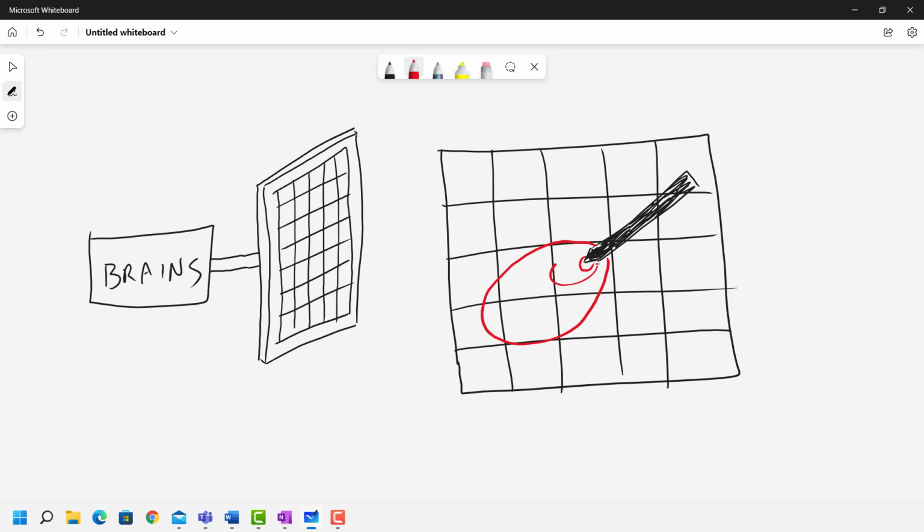So you can see it's no longer just the circle. It's kind of smaller toward one side and much bigger toward the other side. And so this, if you look at how it's going to affect the coils, is how the tablet can detect if the pen is tilted, because the shape of the magnetic field as it intersects these coils will look a little different. So at this point, we have figured out how tilt must work. And so far, the pen is still simply an LC circuit.